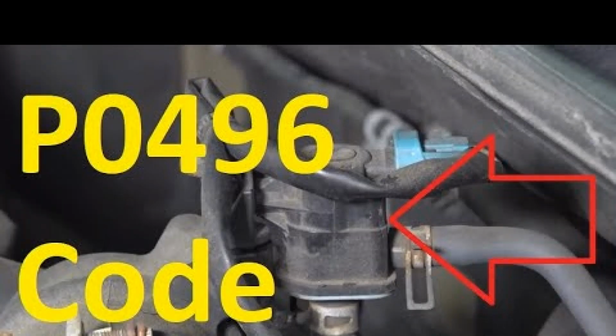Code P0496 indicates that there is a purge flow or more than 10 inches of water vacuum detected in the EVAP system and fuel tank when the purge is not commanded. The water vacuum is very low compared to inches of mercury, Hg. This may be a problem with the tank purge valve circuit, the PCM, etc. Since the fuel tank pressure sensor is the input used by the PCM to detect this vacuum, it's possible that the FTP sensor is slightly out of calibration, which could be causing this problem.